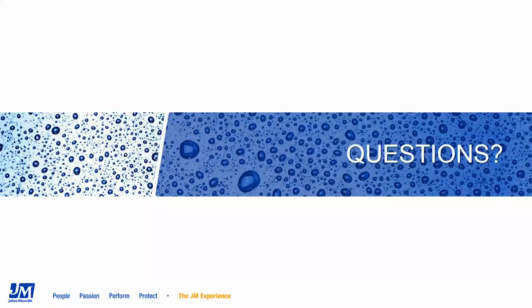All right, thank you. Marybeth, the next question is for you: what temperature limit do you consider the upper limit for CUI? So I think in this presentation, we say that the severe range is 100 to 350 degrees Fahrenheit. That's not saying that you wouldn't experience CUI at other temperature ranges. It's just that between that range is where it's likely that you could have liquid water, and liquid water present is always going to accelerate the risk for CUI.